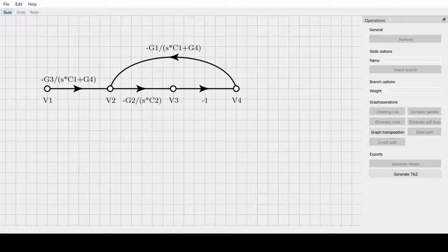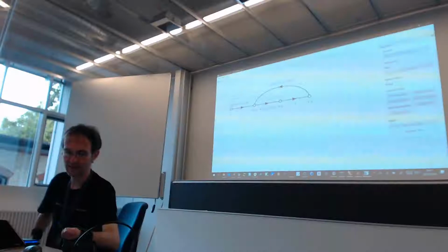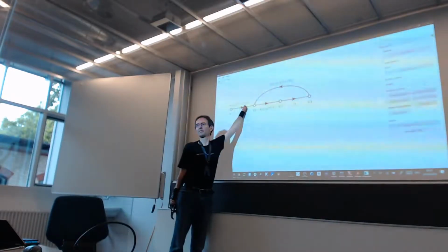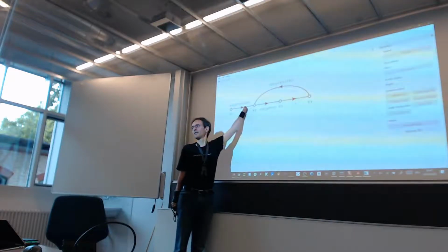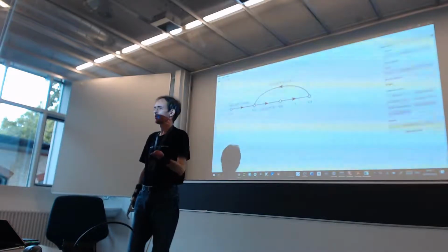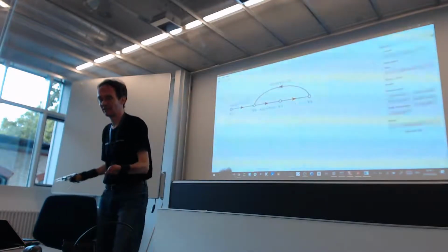Very simplified, because now, of course, you do not have more loops that are necessary. I have kind of included one of the loops here already in this signal flow graph. So I said, I take the G4 as a feedback conductance. So I put it into the driving point signal flow graph as a driving point impedance or driving point admittance.